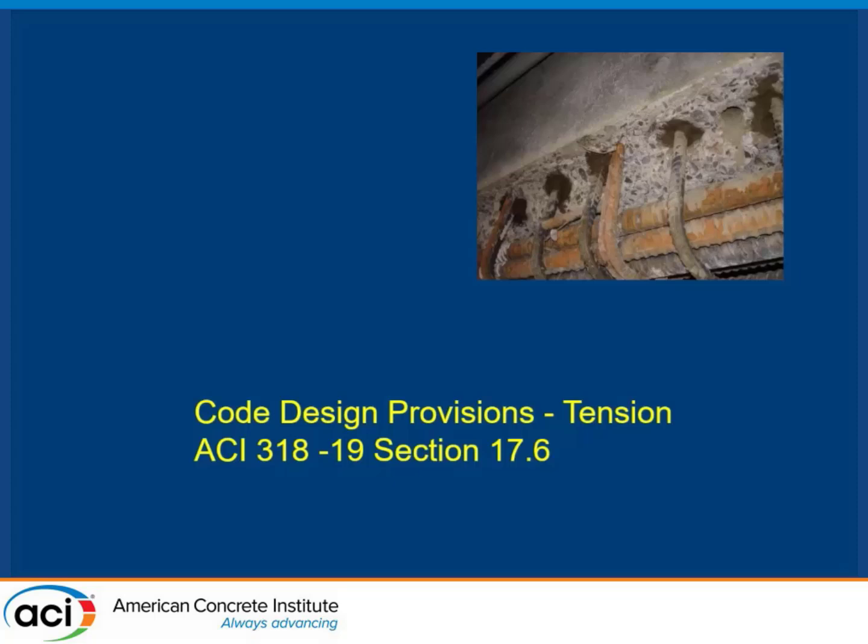Well, the Big Dig, and we're all moving ahead here, but that's all right. So the question was, and I've heard it go both ways, does it take more time and effort to use one particular mechanical anchor, or more time and effort to use an epoxy anchor? I think contractors prefer epoxy anchors for the most part, but now with the requirement of being certified and stuff like that, that's kind of taken some of the fun out of it. The mechanical anchors are real quick to use, but like you said, some of the less expensive anchors out there might not be all that great in cracks.